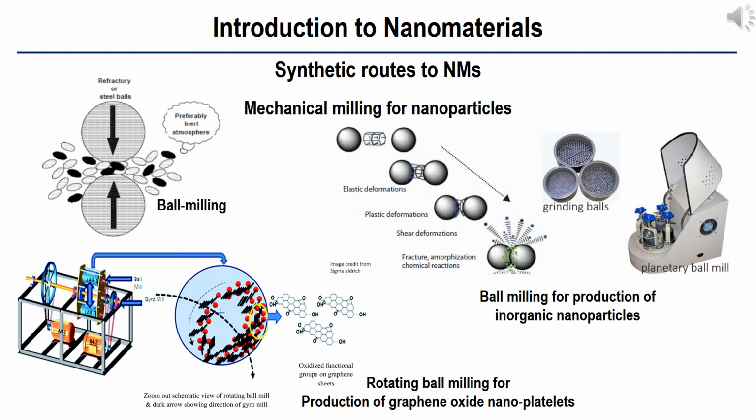Similarly, the serious problems that are usually cited are: 1. Contamination from milling media and/or atmosphere, and 2. To consolidate the powder product without coarsening the nanocrystalline microstructure. In fact, the contamination problem is often given as a reason to dismiss the method, at least for some materials.